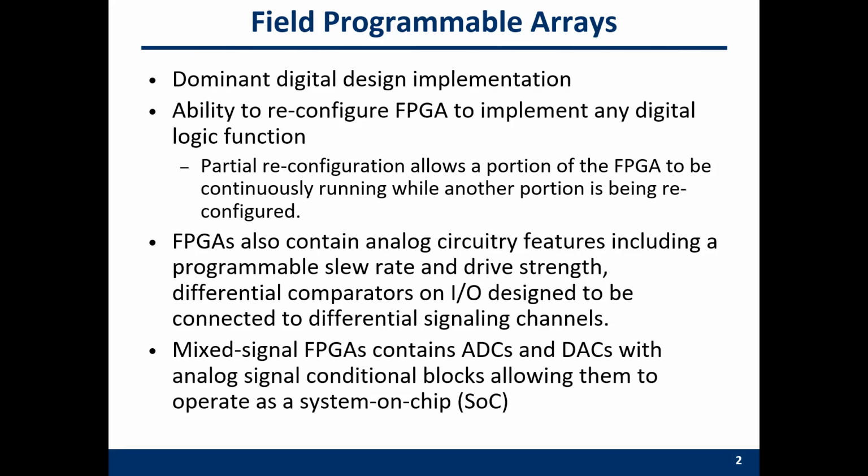So we need some reconfigurable platform to debug and test our designs. Then we need FPGA. FPGA has the capability to reconfigure its components to implement any digital logic function. Partial reconfiguration allows a part of the FPGA to be running, and another portion can be reconfigured.